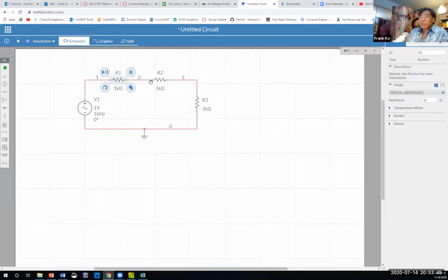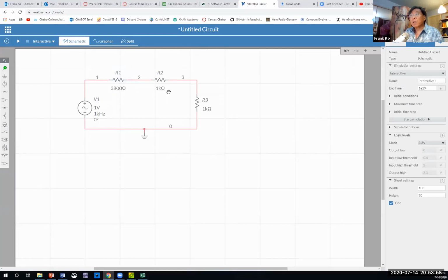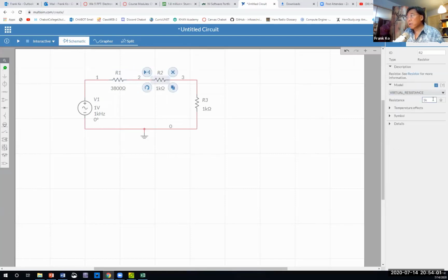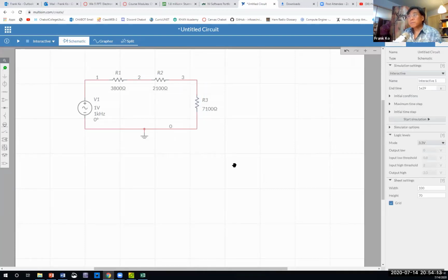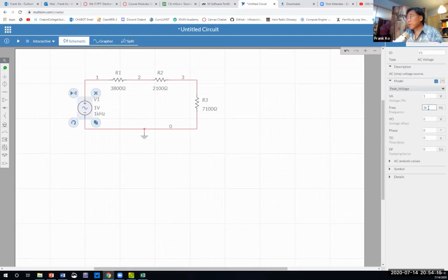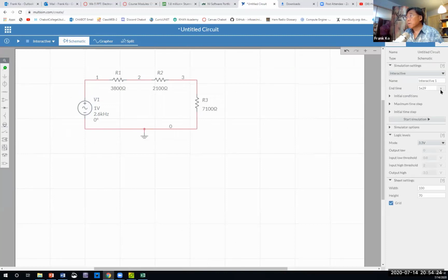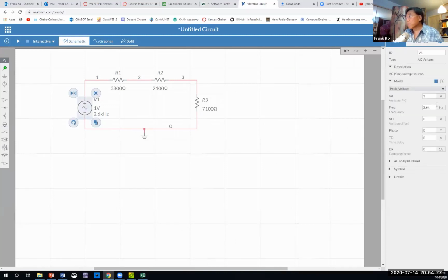I'm going to double click on this guy, and I'm going to make this 300. I'm going to make this 3,800. Double click this guy and make this guy 2,100. Double click this guy and make this guy 7,100. And double click this guy, and I want to change the frequency to 2.6K, and I'm going to change the voltage. I want the voltage here to be 15 volts.